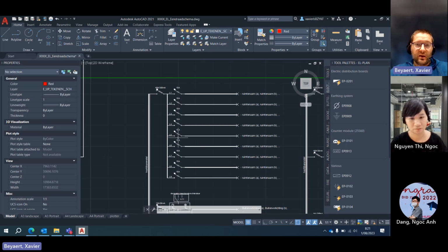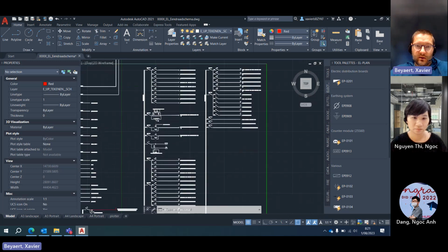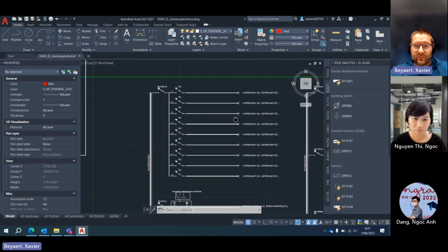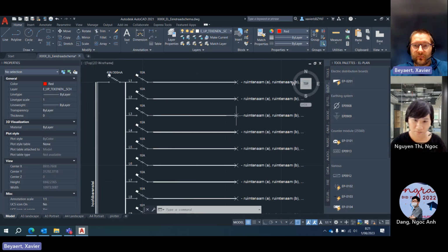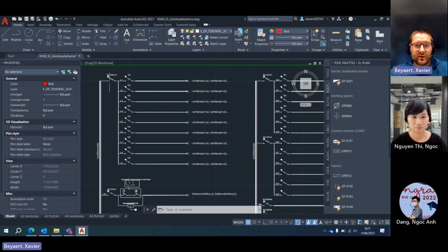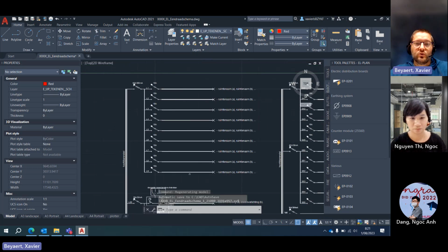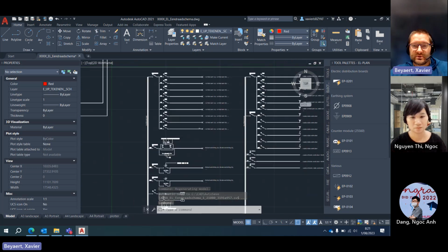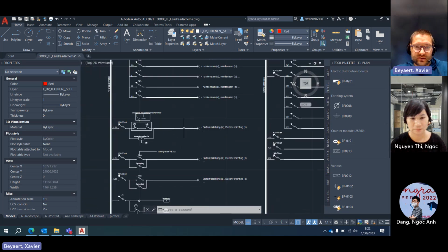So you have 3 times 30 amps per phase. So it's lower than the 40. So it's okay. And also, if you have a fault on this one, an earth fault on one departure, the differential will disconnect, and then you only have a failure of 9 circuits and not more than that. So that's a bit the reason behind it.